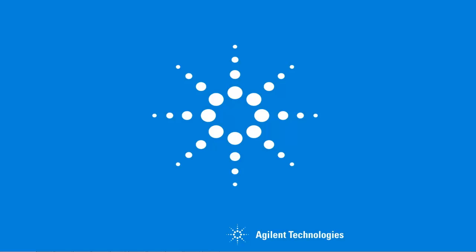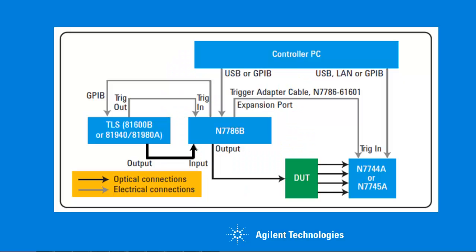The required connections for the IL PDL measurement are shown below. Both the polarization synthesizer, the N7786B, and the multiport power meter are connected directly to the control PC. There's a GPIB connection between the N7786B and the tunable laser. Additionally, we have a trigger connection. There's a BNC trigger output on the rear of the tunable laser, which is connected to a BNC trigger input on the N7786B. And there's also a trigger connection between the N7786B and the multiport power meter.